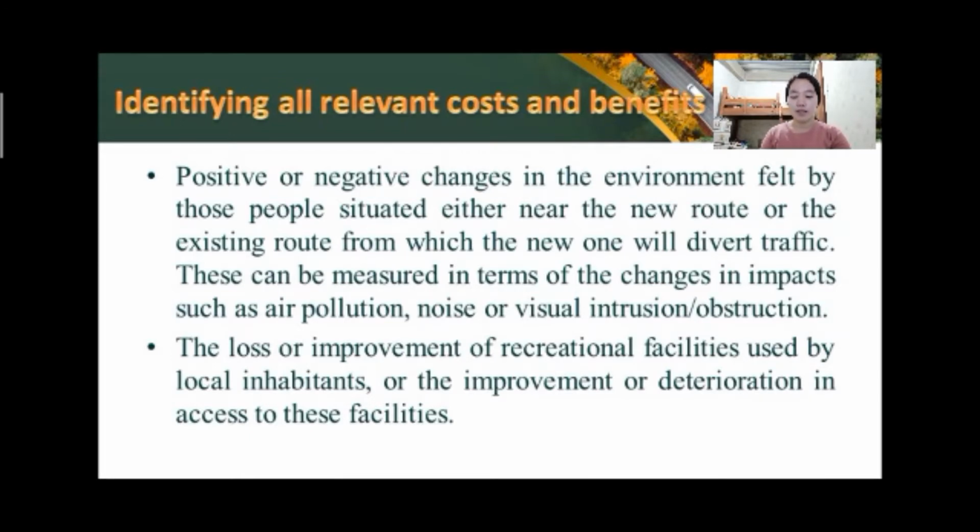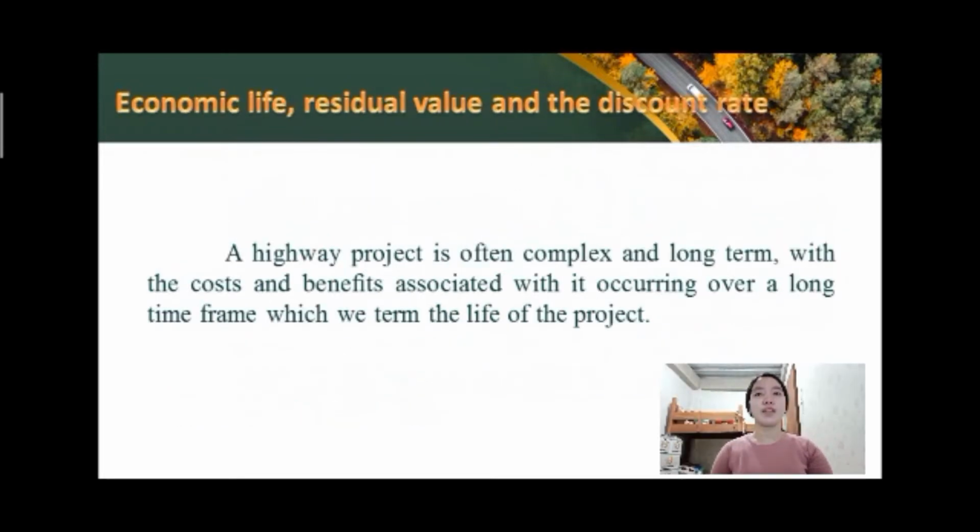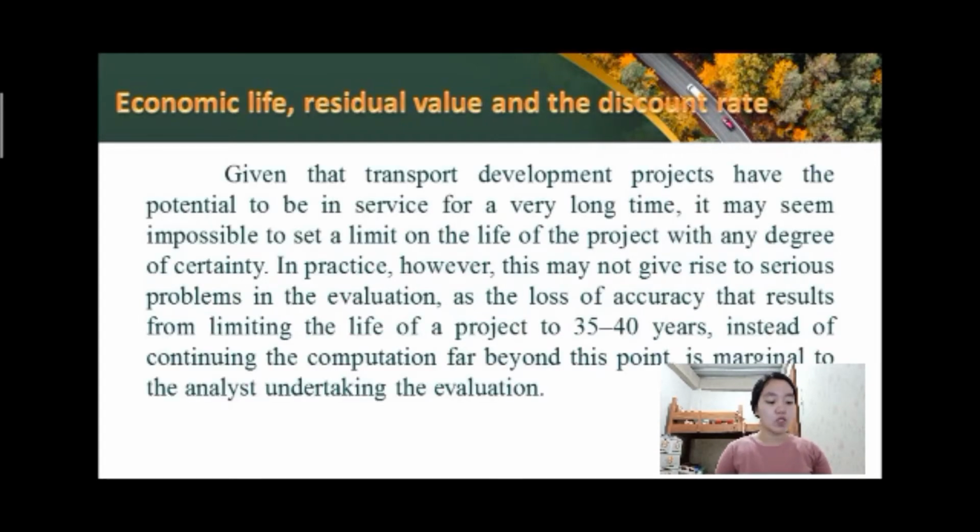The costs associated with the proposed highway installation can fall into similar categories. Economic life, residual value, and the discount rate. A highway project is often complex and long-term, with the costs and benefits associated with it occurring over a long time frame, which we term the life of the project. Given that transport development projects have the potential to be in service for a very long time, it may seem impossible to set a limit on the life of the project with any degree of certainty.